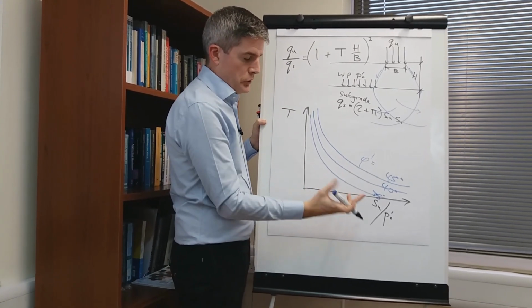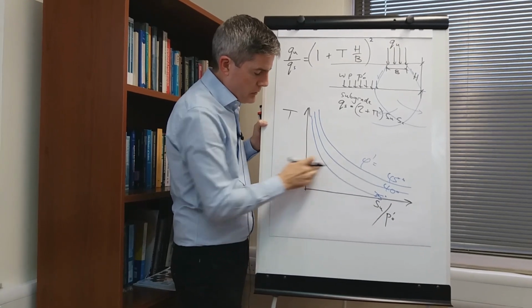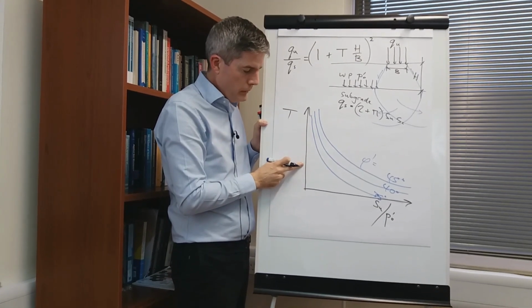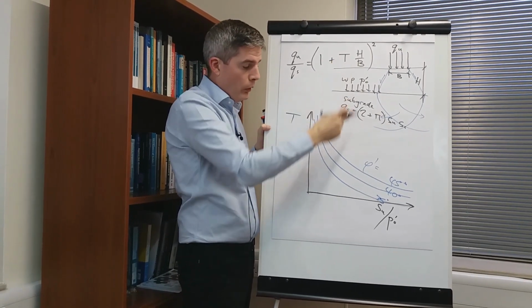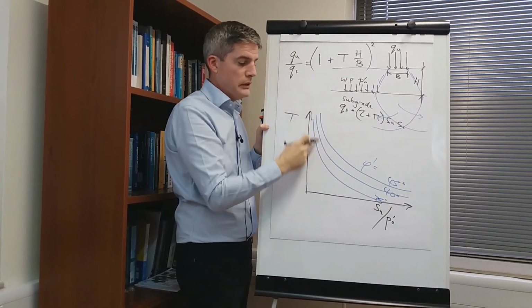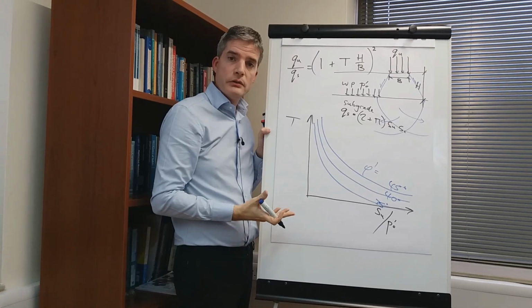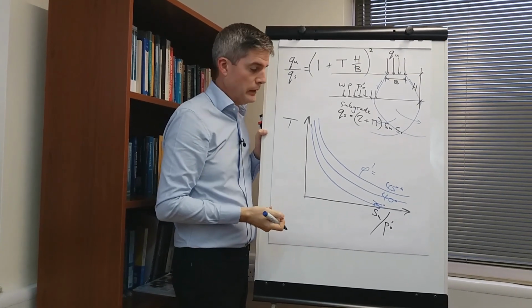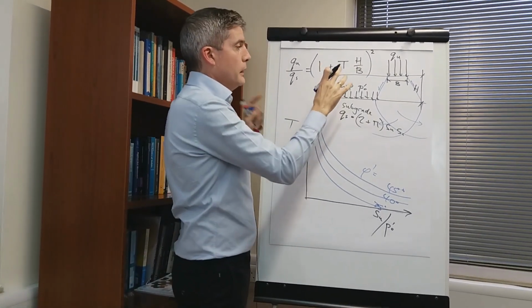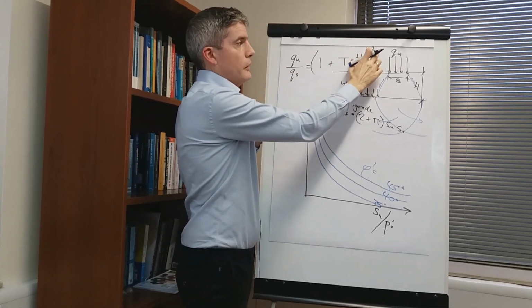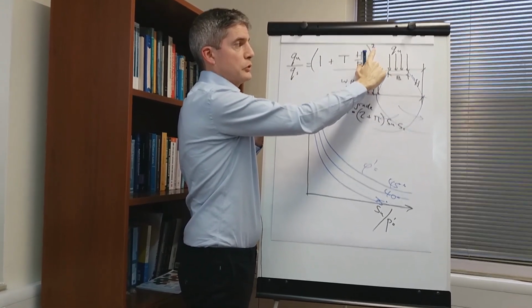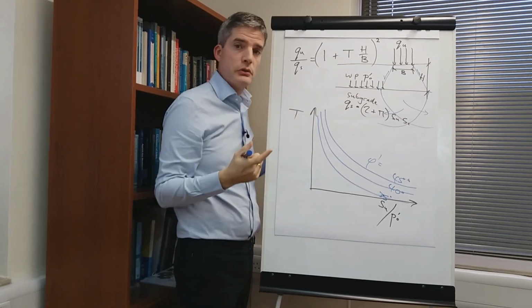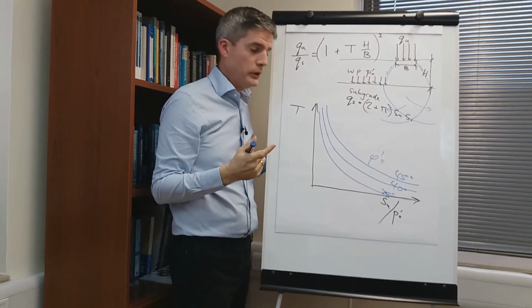You could use this as a chart: you have your SU value and simply read off your value of T and put it into that equation. Or you can use the equations of these lines and program it into a spreadsheet very easily. Now remember, this is 1 for a strip and 2 for a square. What about in between? You just do a linear interpolation between the two.